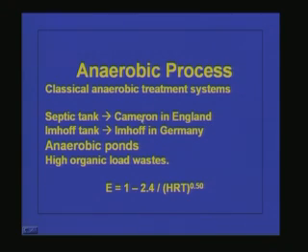A septic tank is nothing but a tank which allows the settlement of suspended solids in wastewater, and the settling time is so large, that means it gives a time of 5 to 10 days. During this period, whatever suspended solids are present in the wastewater will settle down, and the tank will not have any oxygen supply. So the sludge settled at the bottom of the tank will be under anaerobic conditions. At these conditions anaerobic bacteria will prevail and the solids will undergo anaerobic degradation.